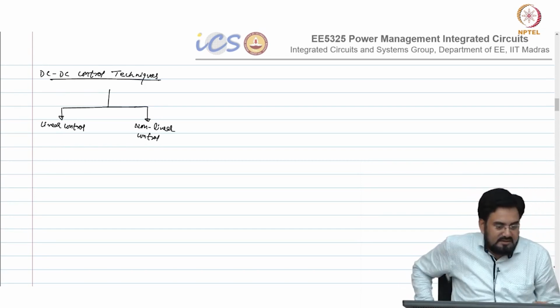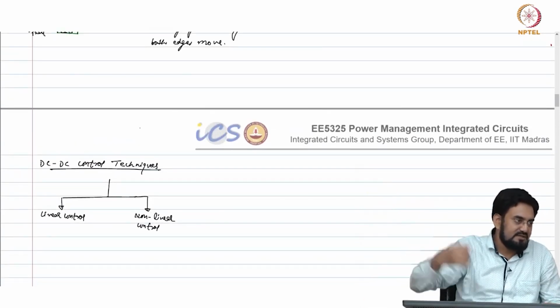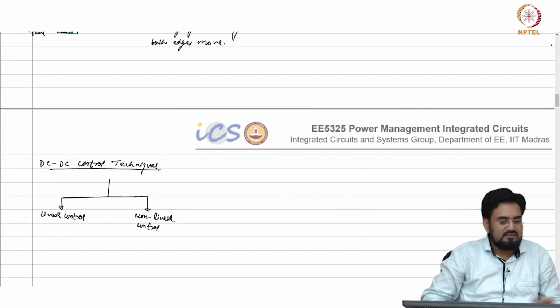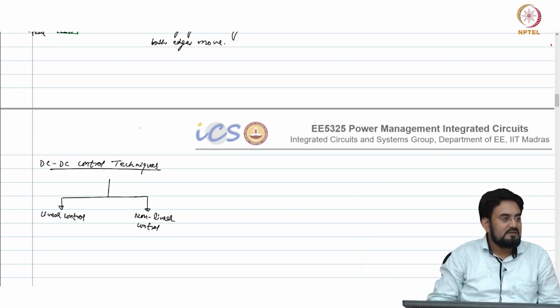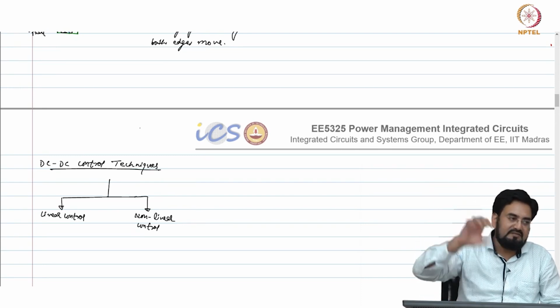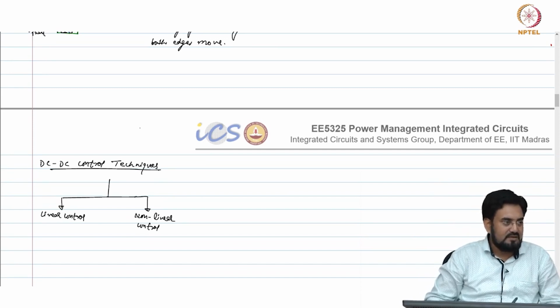If we know that we just have an LC power stage, power switches, you just feed the duty cycle and get the output, PWM. Yeah, so your load is varying. If your V in and V out is fixed, then you can calculate the duty cycle based on your V out by V in ratio.